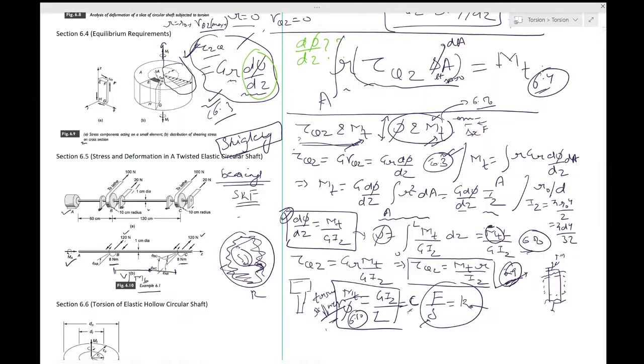So in this case, this S is your shaft, even though I called it the stator in the earlier case. Now this is the part which is rotating, and this is the outer casing which is constant. So the fluid will try to apply a friction force in this direction because it is rotating like this, and that's how you would experience these external shear stresses. But because you have a bearing, they are assumed to be negligible between them.